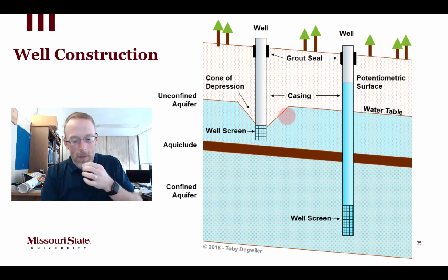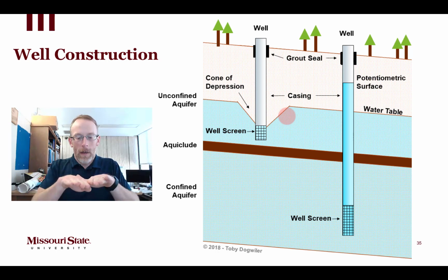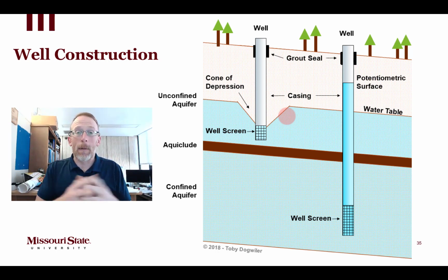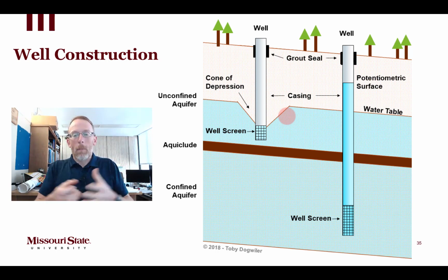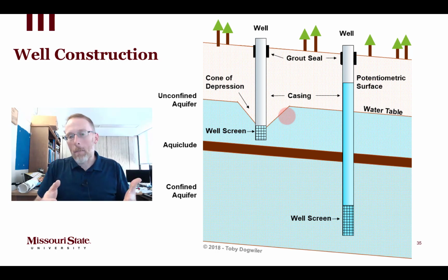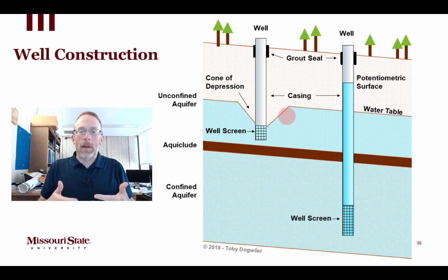If you give it a second, if you suck really hard, create your cone of depression, and then stop, the top of the ice cream will level out and the cone of depression will disappear. Same thing happens in a well. If you pump really hard, you actually pump all the water immediately around the well out faster than new water can flow in, and you'll get a cone of depression. If you stop pumping, things will catch up, and the cone of depression will fill in with water from the